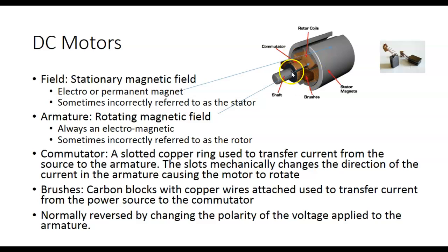So by the way, the thing that does the switching is called the commutator. And it's going to be slotted so you can actually see it on that DC motor. And the brushes, you can see what happened on that one is that thing was sealed and it was actually twisted to get in there, and we didn't, and the brushes just finally wore out on them. So the brushes are gone.